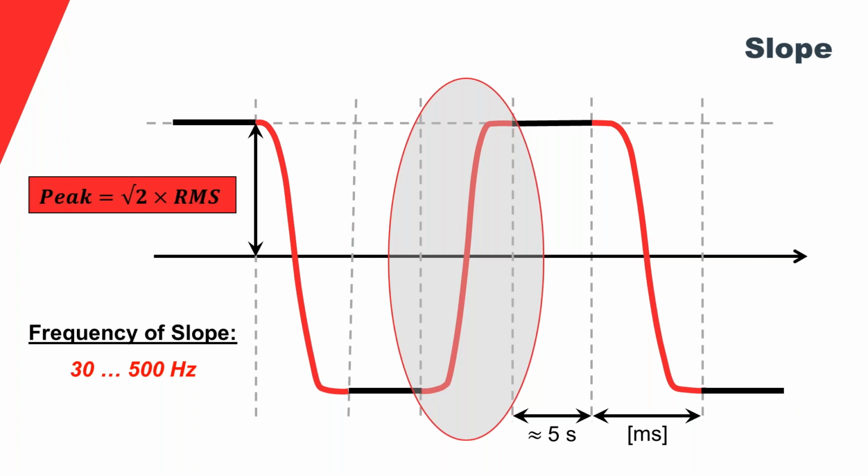The difference is typically that because you have this higher voltage stress in the insulation and a continuous wave shape compared to the non-continuous wave shape of damped AC, the magnitude of the PDs is higher. So if you test a cable, everything in the mapping will be the same between damped AC and cosine rectangular, except that the picocoulomb values will be higher for the cosine rectangular for the slope.